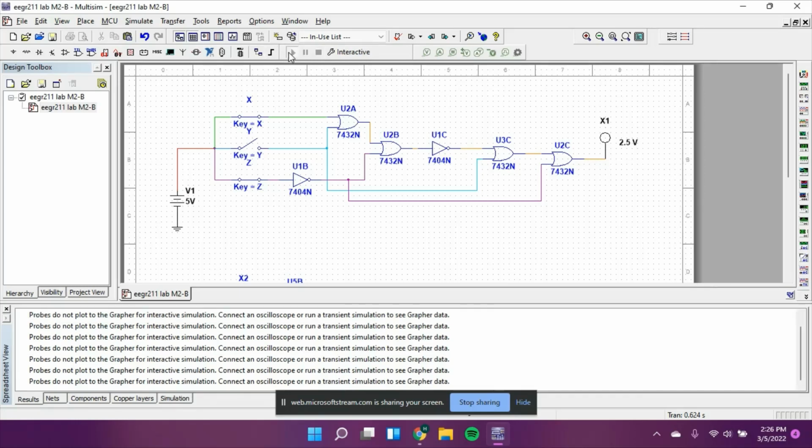We can test that right now, and this seems to be true because x, the switch is closed, same with z, so they are going to be 1, and y is open, so its input is going to be 0. And if we were to change this at all, let's say let's open x, the light turns on.